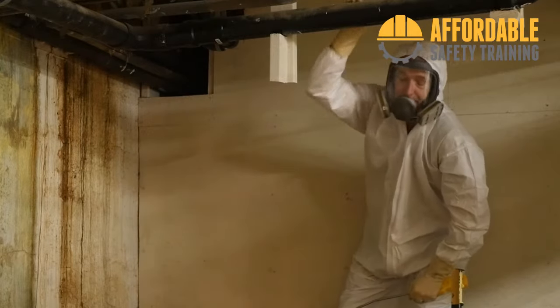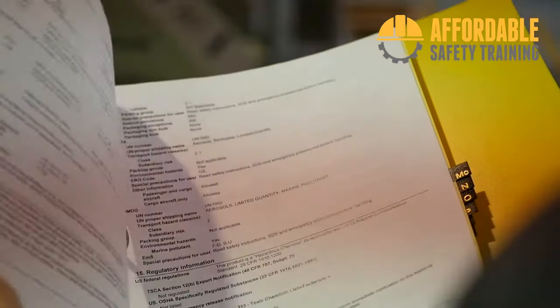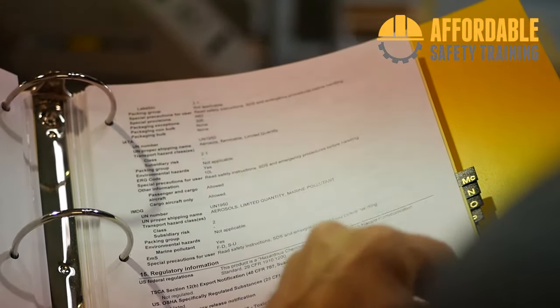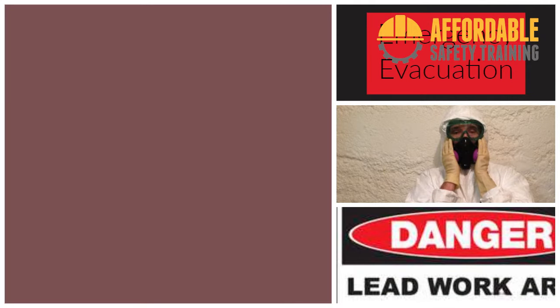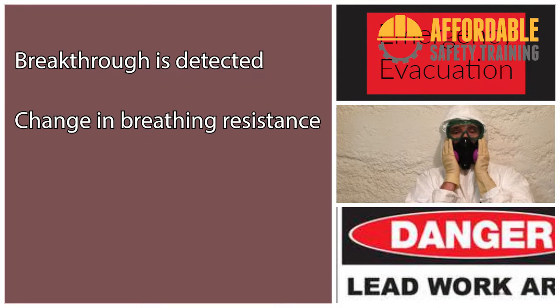Keep in mind that many chemicals do not produce a notable odor. The safety data sheets explain the symptoms of exposure for each chemical. Be familiar with them, the information may save your life. The worker should leave the hazard area if breakthrough is detected, if there is a change in breathing resistance, or signs of leakage past the seal.